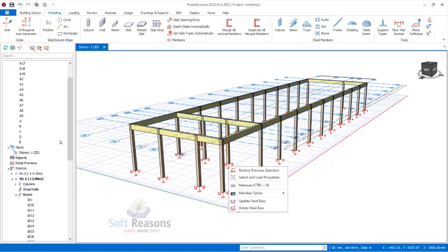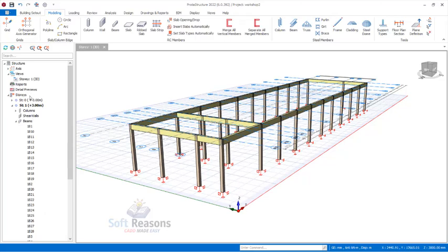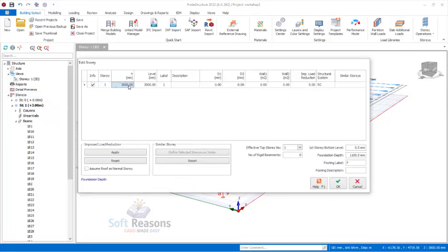Okay, so let's go into the settings to make sure that we are on the same page. So you click here, right click, or you can come to the building setup here and then come to stories operations. So here you can get to edit stories, okay, and make ordinary editing successfully. So select on the stories, right click and click on edit stories.